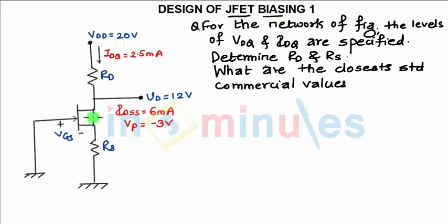First we need to find which type of JFET it is, N channel or P channel. So the arrow is from P to N. When it is forward biased, current will flow from positive terminal to negative terminal. So the arrow indicates the flow of current when it is forward biased. That means the right hand side is N, so it is an N channel JFET.